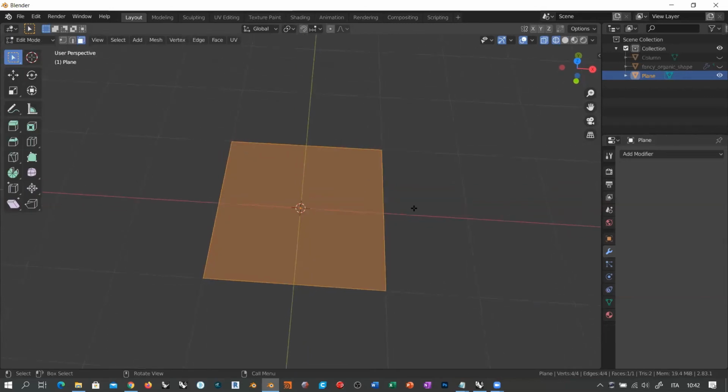Okay. So in order to subdivide this by hand, I want to use the loop cut tool, but not by hitting this button here. So I'm still in selection mode. Loop cut can also be applied by clicking Control R. Control R has the same meaning as loop cut.